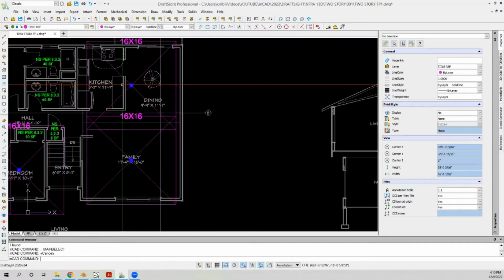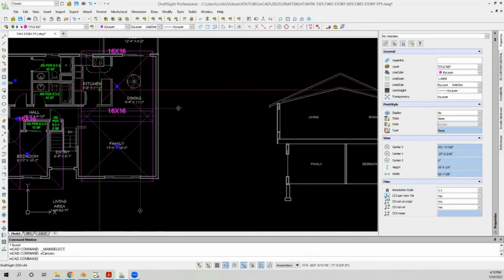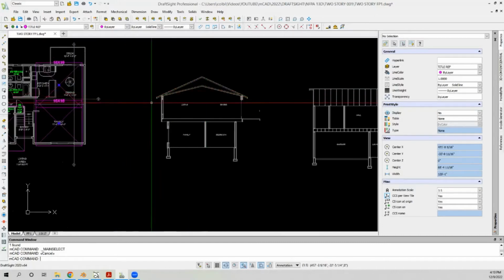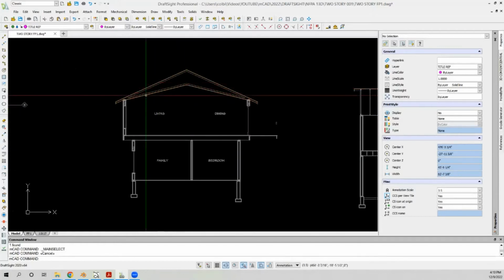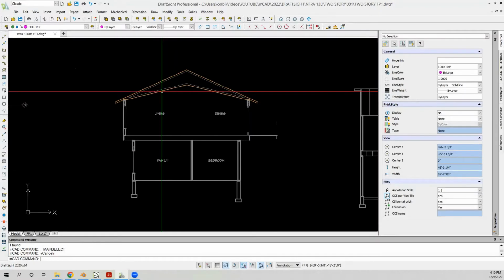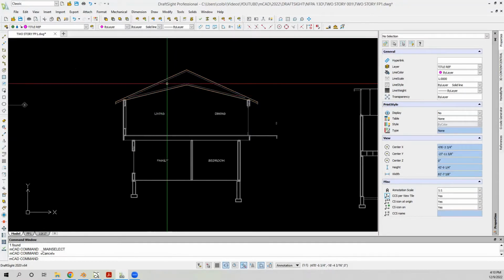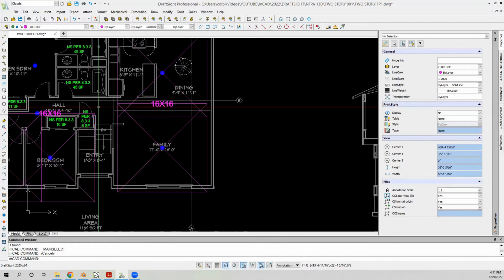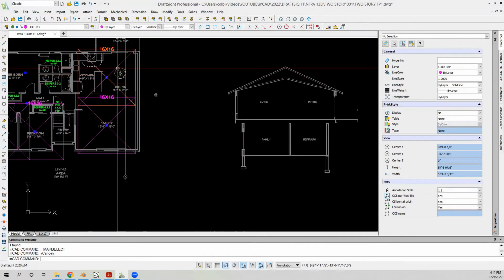Oh, something we need to think about, actually. So this is a slope, and you have to measure, this is it right here, actually. This section A, that's this section right here. And it's a slope. That's a scissor truss. And when you are measuring the distance between sprinklers, you do it on the slope. And this drawing we're doing is flat, in line with the flat ceiling, but it doesn't correspond with these slope ceilings.